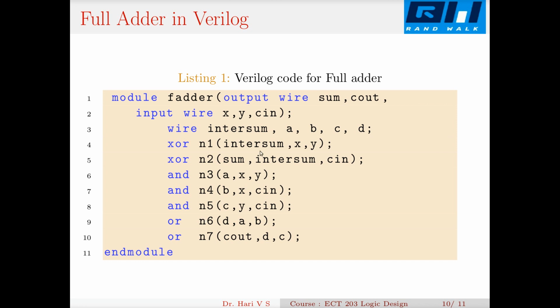So what I do is I give an intermediate variable a, that's an internal net d. So ab is given to an OR gate, that gives me d. Then d is ORed with c to get my c out. The complexity comes because instead of using a single gate, you can define some 3 input XOR and 3 input NOR and do that.